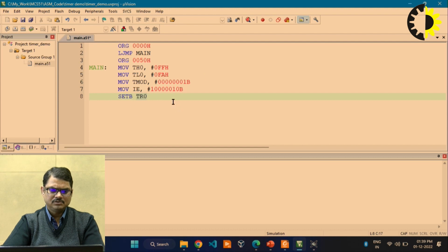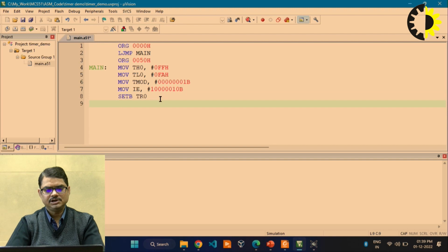So what will the microcontroller do till that time? We need to provide some useful instruction to this microcontroller, because it is on and actively executing instructions. So we are creating an empty indefinite loop. To create it, I am writing a label here, and I am using SJMP.